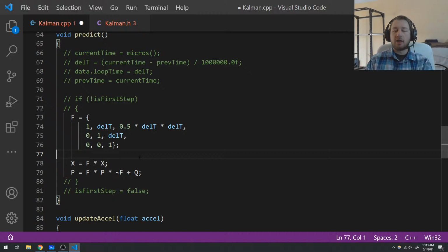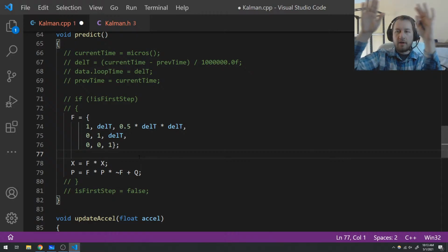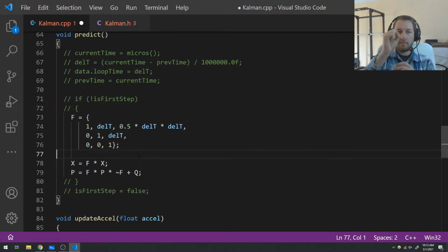So we need a way to get the Kalman filter to say, okay, we've predicted this many steps, and I feel like I'm in this location, and I'm not very sure about it. And then this is where the update comes in, where you take a measurement at this point and you say, oh, you thought you were in the middle here or anywhere in this circle, and the update equation comes in and says, well, I think I'm actually somewhere here in this circle, and this is my certainty.